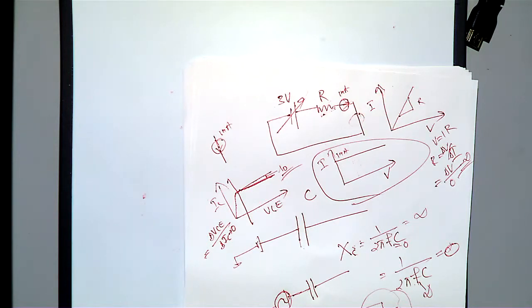Small signal model example. So this is what we have drawn, but when you bend it down, with respect to this line you can rotate this RC and then bring it down, then you can get a clear picture. So when you measure the output voltage, actually you are measuring with Early effect. Then you got this RC, this RO, see both are coming in parallel, because this is ground, this is a ground. So RC and RO. So basically you are measuring the voltage drop across this parallel combination, RC parallel RO, when you have Early effect. When you don't have Early effect, RO equals infinity, so this part is open, and then what you are measuring is a voltage drop across this RC.